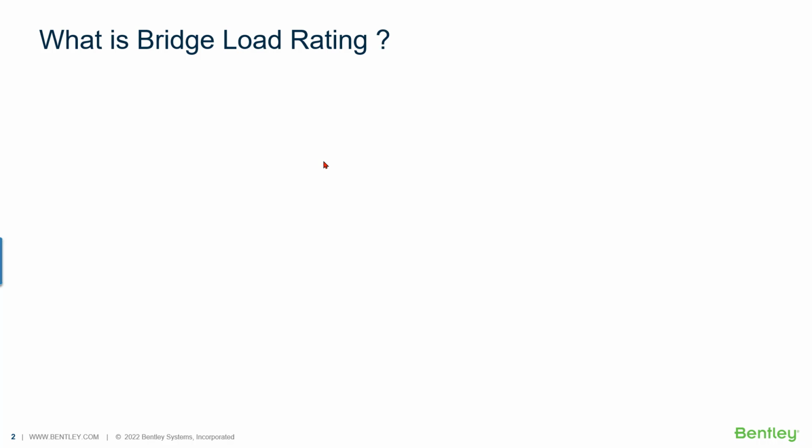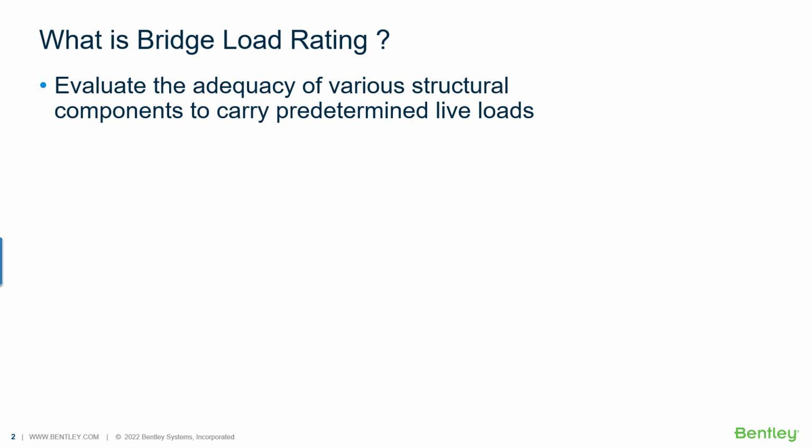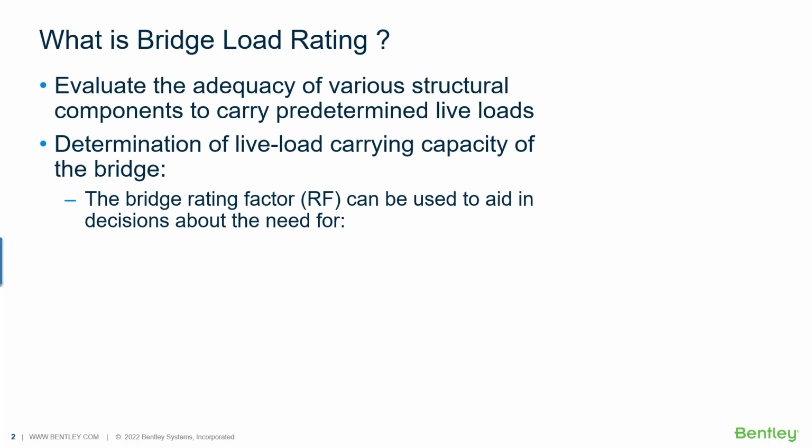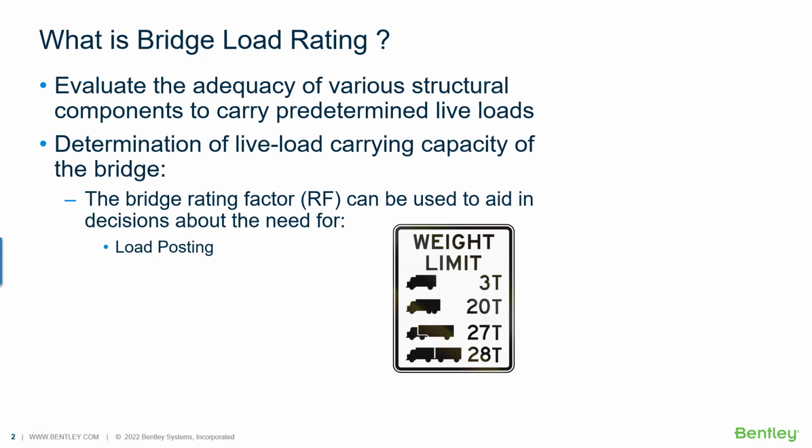First, I will try to explain what bridge load rating is. Bridge load rating is a process to evaluate the adequacy of various structural components to carry predetermined live loads. We can also define it as defining the live load carrying capacity of the bridge. It can be used to aid in decisions between different needs.